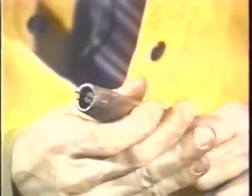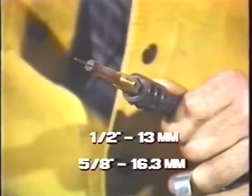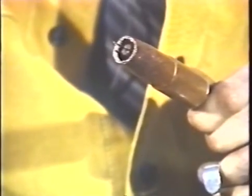The wire stick out should be 1/2 to 5/8 of an inch in length. When you put the nozzle on, make sure the contact tip is slightly recessed. Remember, when using spray transfer, the selection of your MIG gun is critical. Use the information previously provided under MIG gun selection earlier in this tape. Improper selection will result in early torch failure and a high nozzle and contact tip failure rate, which will also influence arc stability.